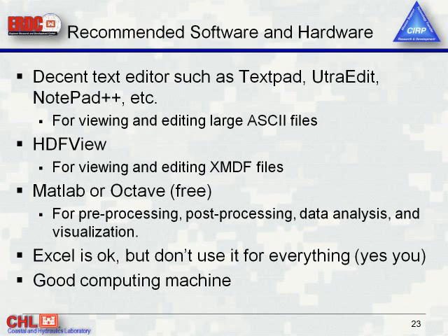Before I go on, I'd like to recommend some software and hardware for everybody. First of all, if you want to do serious modeling, you need to have a good text editor like TextPad, UltraEdit, or Notepad++, for viewing and editing large ASCII files. Also, if you want to edit or view the XMDF files, which are the binary solution files, and even the grid and the model parameters file, you need to have HDFView.